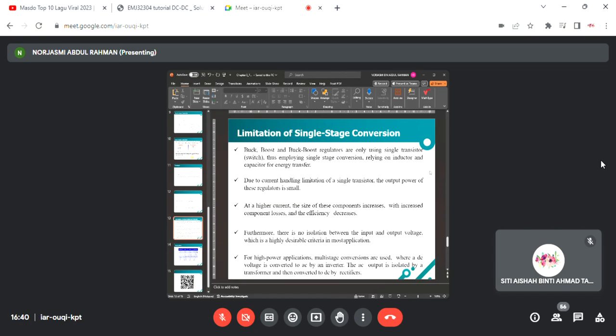The conduction losses deal with the current being handled by the switch, and the switching losses deal with the on-time and off-time losses of the switch. For the on-time and off-time losses, we will take a closer look in next week's chapter, the thermal management.